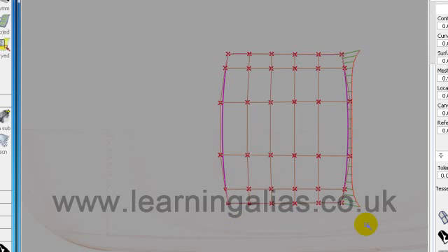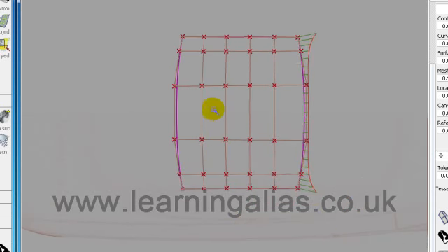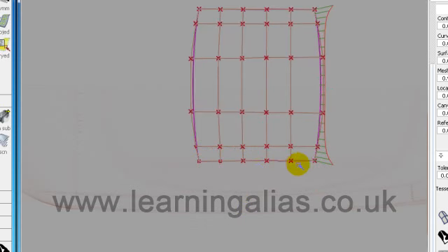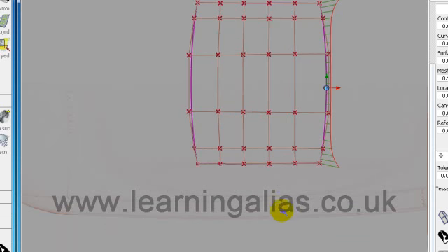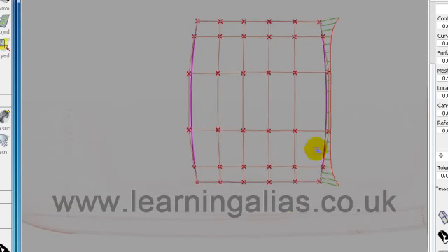Okay, next thing I want to talk to you about is, incidentally, I've put in CVs here since the last video, and the reason I've done that is nothing to do with this surface. It's to give us a 5-degree surface single span to build our cant rail surfaces onto. Just from experience, I know that there's more chance of them working straight off the bat if you have a degree 5 surface rather than a degree 3 or degree 4. So that's a matter of personal preference, but that's the way that I model.